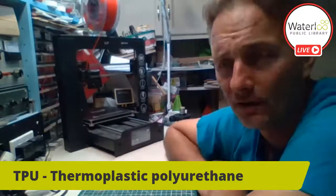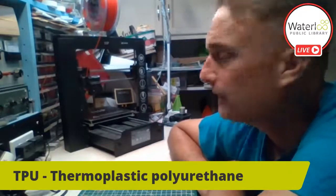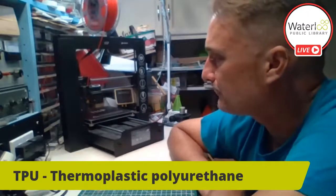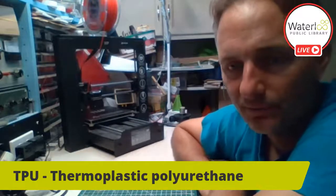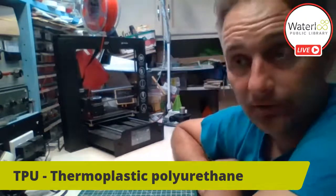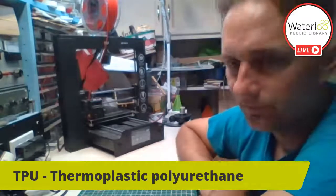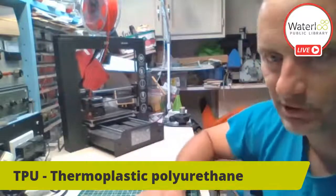Other popular ones, or common ones now, metals. There's lots of metals that they've figured out how to get to work with 3D printers. Now, again, it's just 60% metal and then 40% plastic, so that metal can flow through your 3D printer head. So it's materials like copper, brass, and steel you can 3D print with now as well too, and you can polish them. You can make them look all shiny and nice and fun. They're definitely not as strong as solid steel or solid copper or solid brass, but they retain a lot of the appearance of those materials. So again, you can polish them and shine them up. So right now, that's it from materials.